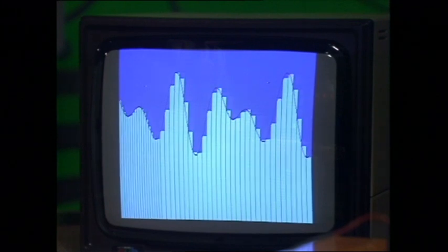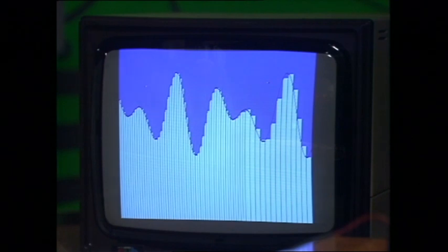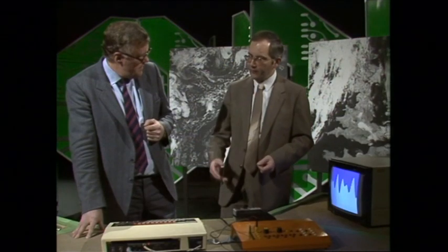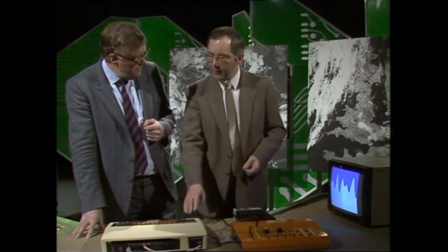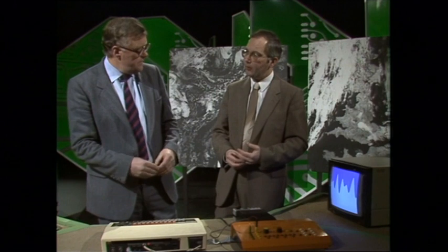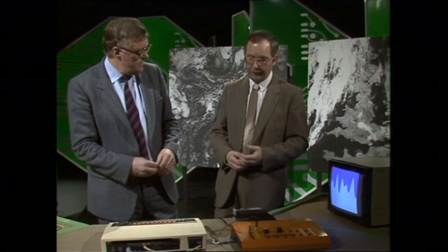And you might think, well, why not go always at a flat-out rate? Simply, it costs money to sample at high speeds. For example, on this computer system, there's an inbuilt analog-to-digital converter which samples 100 times a second, but quite often you need to sample more frequently.